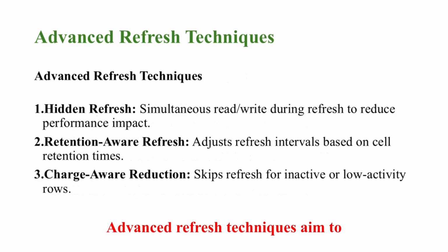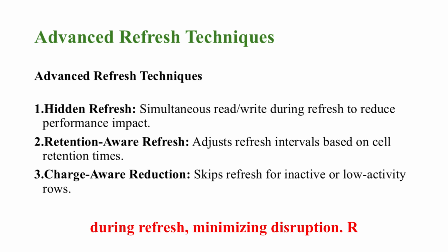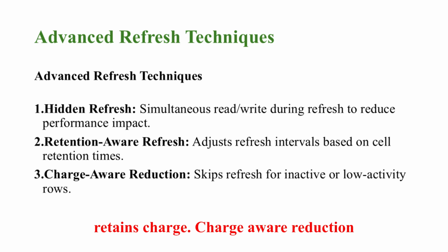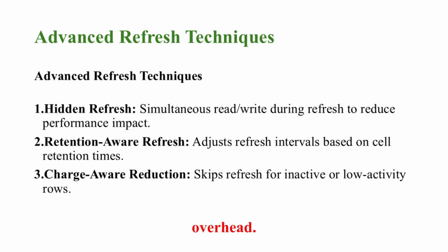Advanced refresh techniques aim to mitigate performance and energy drawbacks. Hidden refresh enables simultaneous read or write operations during refresh, minimizing disruption. Retention-aware refresh adjusts the refresh rate based on how well each row retains charge. Charge-aware reduction skips refreshes for inactive or low-activity rows, significantly reducing overhead.